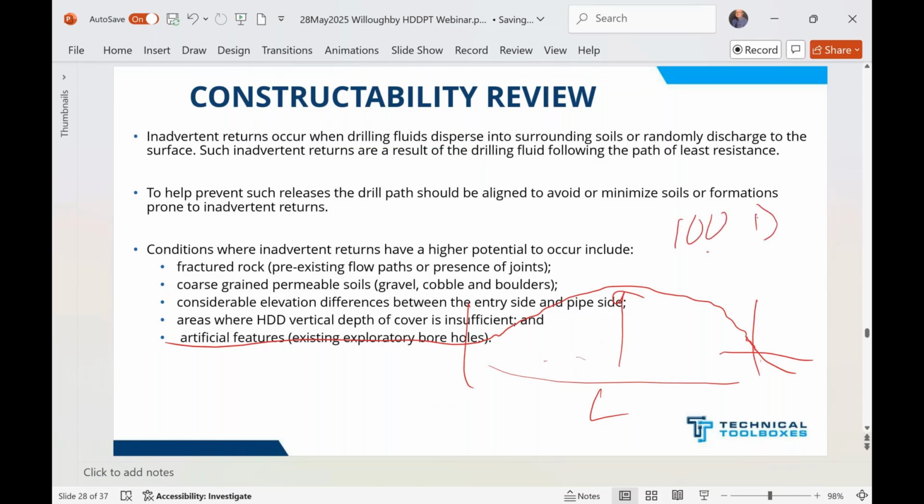So whatever diameter the pipe is, we multiply it by 100. So let's say it's an 8-inch pipe. I would have this right here, an 800-foot arc, 800-foot radius. We use that 100D rule, and we'll calculate that height and that length. Now, we'll calculate what we call the bending stress to that pipe.